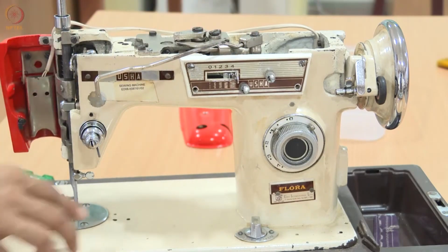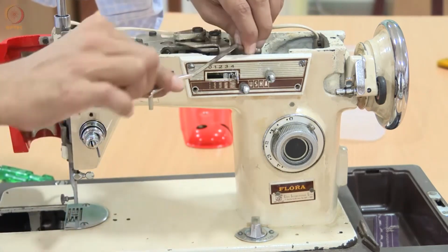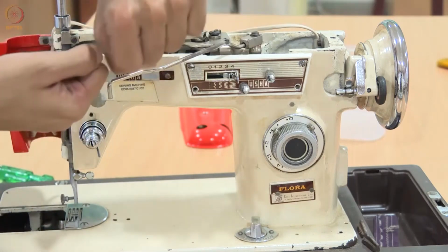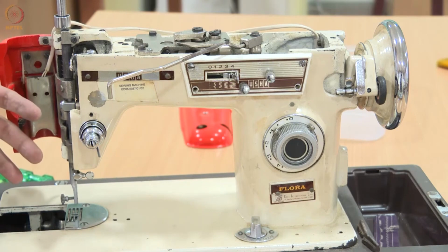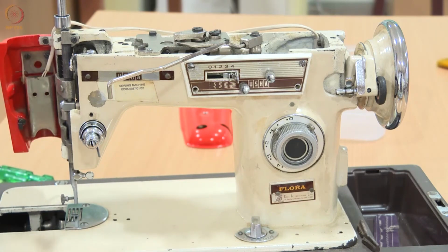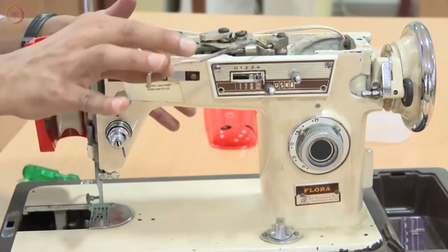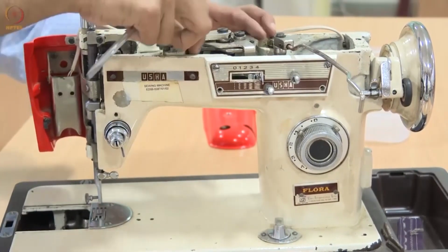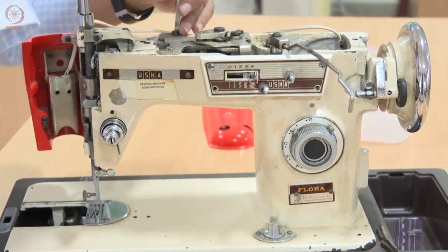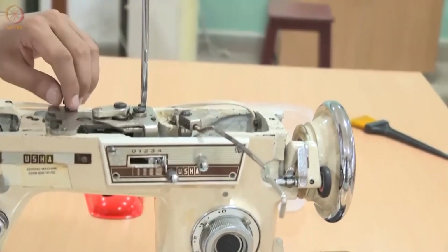Belt drives typically are used, you will find them in sewing machines. Typically, these kind of rigid rods are preferred because belts will tend to elongate over time, and then you lose the synchronization between different elements, different sub-assemblies of the machinery. So typically in older machines, all the linkages will be made of rigid links like this. Now let us proceed to dismantle the top part of the mechanism, the interesting bits.